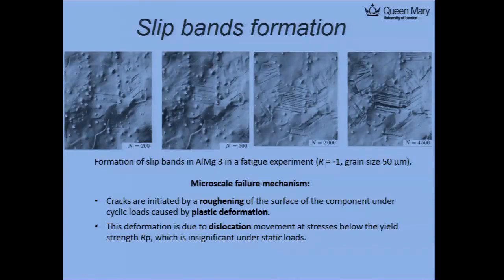So dislocation movements occur below the yield strength. Bear in mind, in this case, you probably apply less than 30% of the yield strength on the material. But still, you have this crack initiation after several thousand cycles, and eventually it will lead to faster fracture. This small plastic deformation accumulates and eventually initiates a crack. So this is a very standard example you should remember.